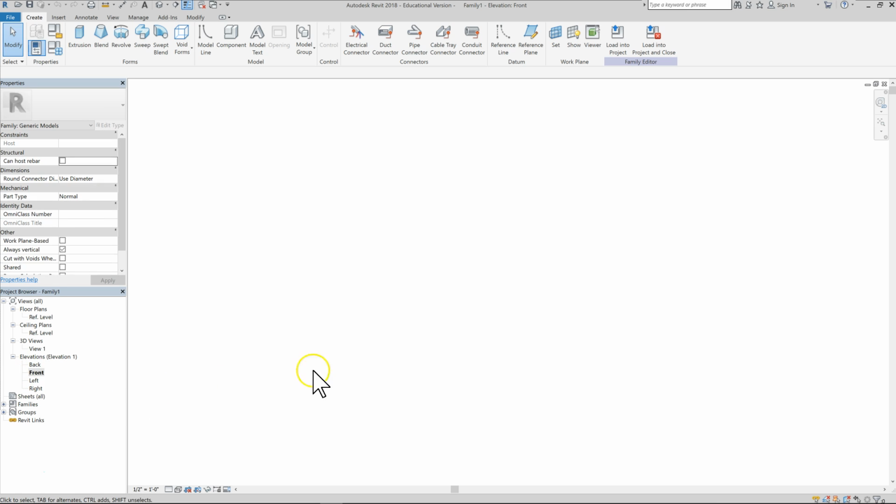Of course, to get there, you always have to double click. Now, there's a little quirk here in the software: when you first go to any of these views for the first time, it doesn't show your drawing plane. So click on the zoom button, or the little arrow right below it, and just select one that's different than the one that's already selected. Right now it says zoom to fit, so I'm going to zoom fit all. And then I get what I'm supposed to have.